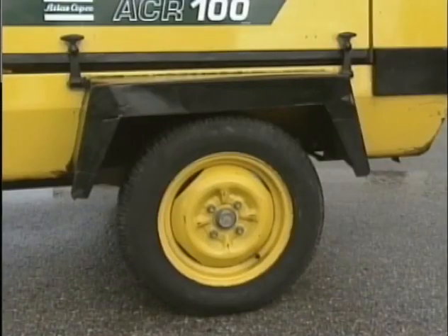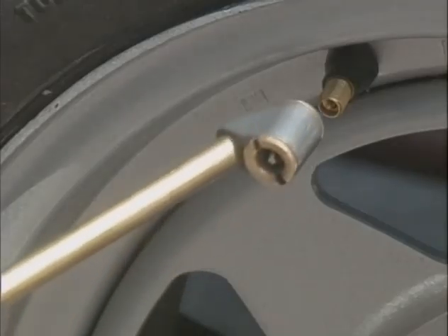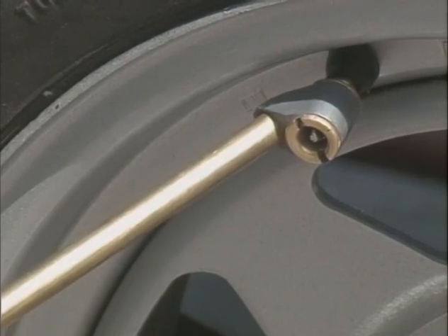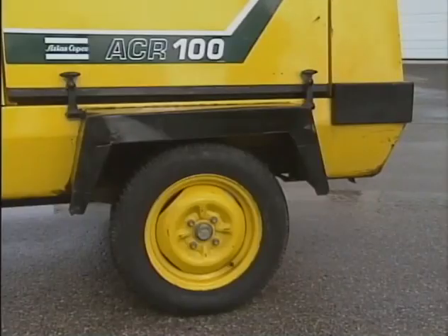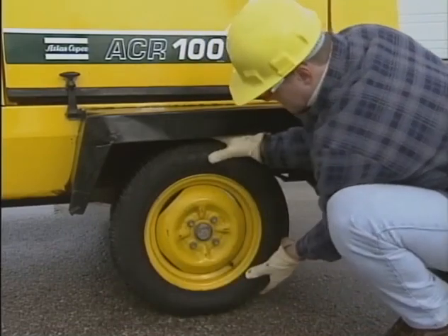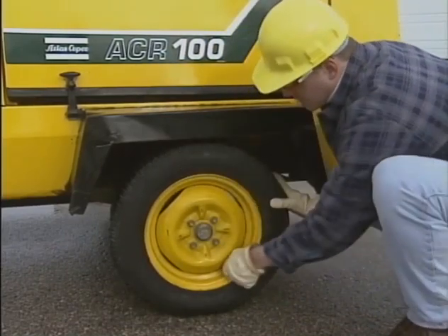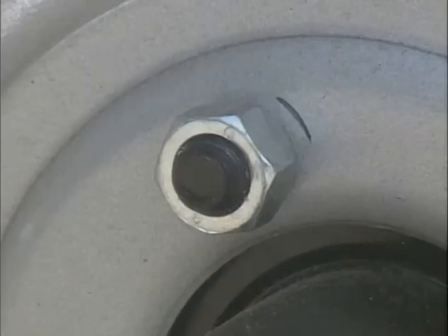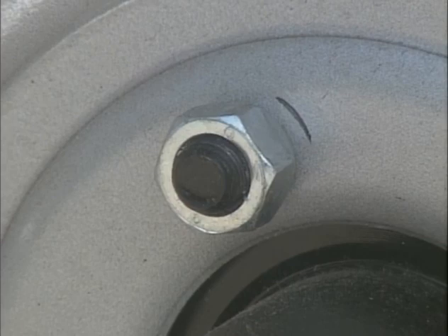Tire maintenance. Explosive separation of a tire and/or rim parts can cause serious injury or death. Always follow the manufacturer's recommendations or see your tire supplier. Always maintain the correct tire pressure. Do not inflate the tires above the air compressor manufacturer's recommended pressure. Inspect tires and wheels prior to moving the compressor. Do not tow with high or low pressure, cuts, excessive wear, bubbles, damaged rims, or missing lug bolts or nuts. Maintain wheel lug nuts tightened to manufacturer's recommendations.